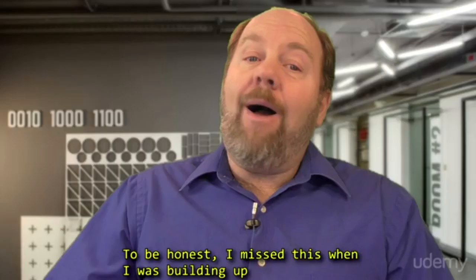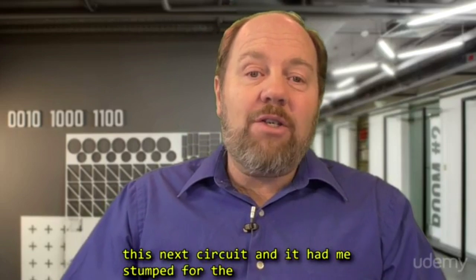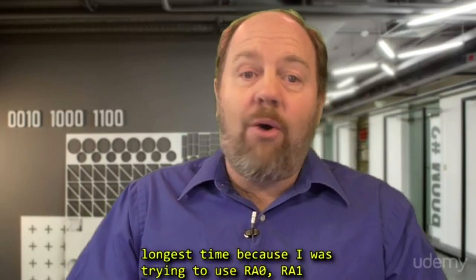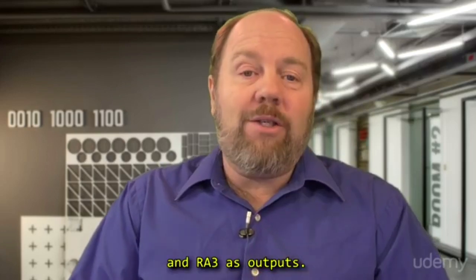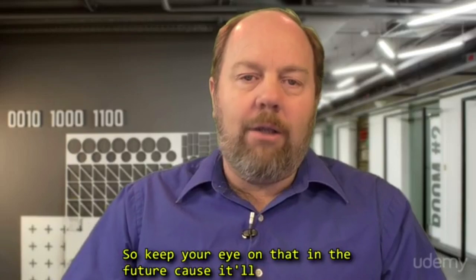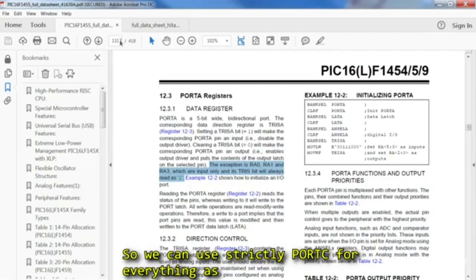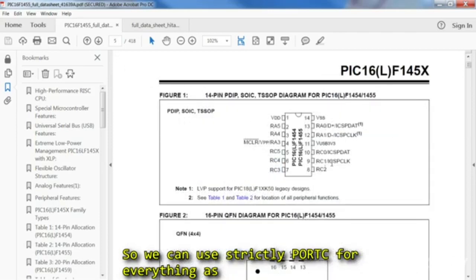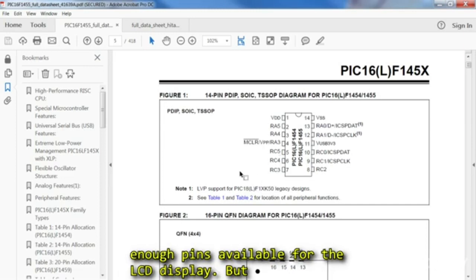Now, to be honest, I missed this when I was building up this next circuit, and it had me stumped for the longest time because I was trying to use RA0, RA1, and RA3 as outputs. So keep your eye on that in the future, because it'll mess you up. So we can use strictly port C for everything, as those pins can all be outputs, and we have just enough pins available for the LCD display.